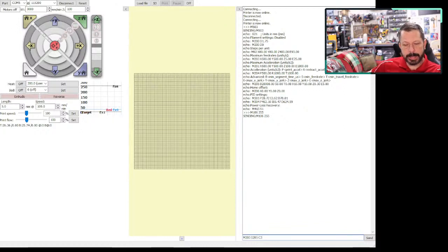Now, there are other parameters that I can put on this command. If I have a different heater, like 2 extruders, I can tell it I want to do E0 or E1, and so there are other parameters. This is all I need to get the one hot end that I have to cycle 3 times around 205, and the data will be collected and processed to calculate new values for P, I, and D. So PID autotune start, that's a good sign.